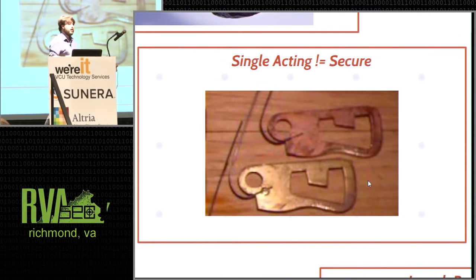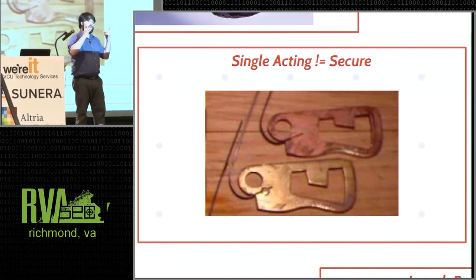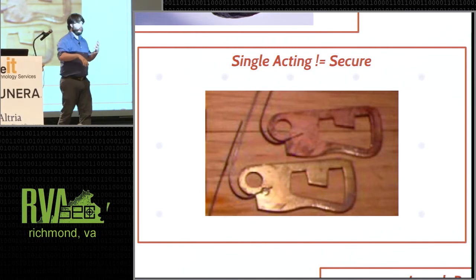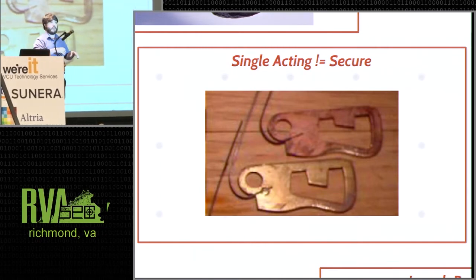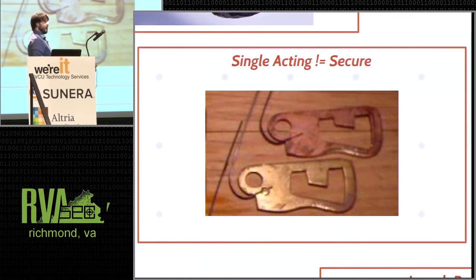All right, so that's all well and good, but a single acting tumbler mechanism, which is now what we call this type, is terrible. Because you could just lift that lever up as high as you wanted and then manipulate the bolt back and forth. There was no upper limit on it, so you weren't lifting it up to the right height, you were just lifting it up. So we then get enclosed tumblers,